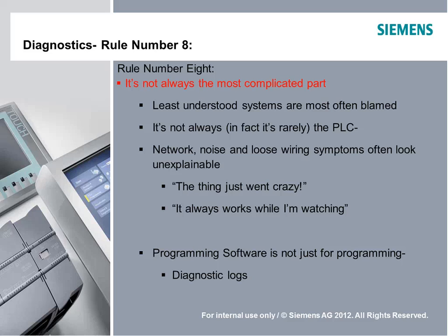So the diagnostic log's invaluable. We can actually see if there's a network fault that's happening currently in the programming software I just showed you, we would actually see a red wire, and we'd know exactly where the problem was. If everything is green, once again, back in the diagnostic buffer, and it will tell you where to go look.